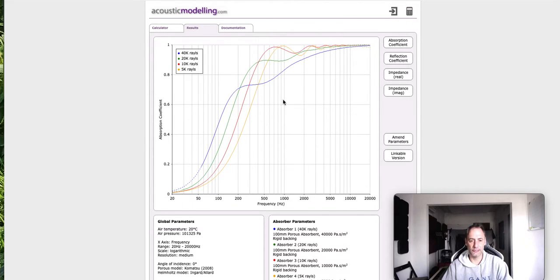So this difference is actually becoming less evident. And perhaps in this case I wouldn't pick this material. I would probably use this material over here, so maybe 30 kilograms per square meter of rock wool or an acoustical foam, instead of the high density.